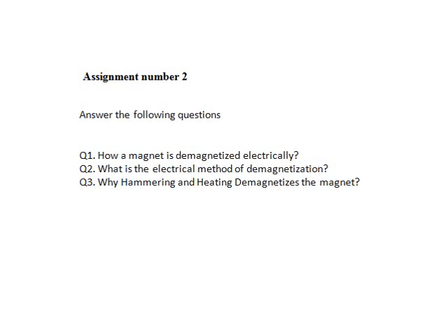Then for magnetization, you have to use DC current, and you have to place a steel bar or any magnetic material you want to convert into a magnet in a solenoid and provide a DC current.